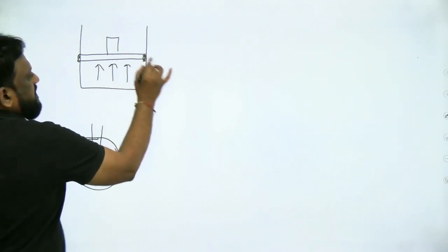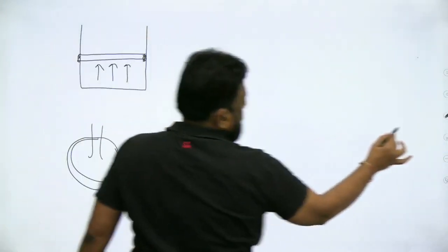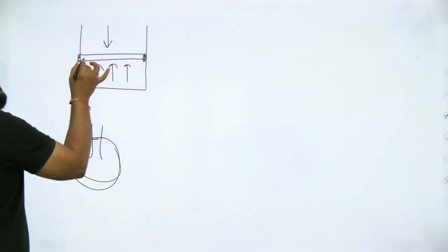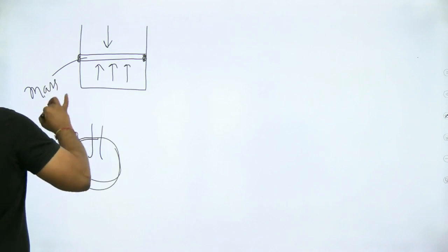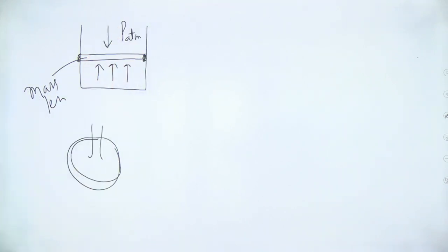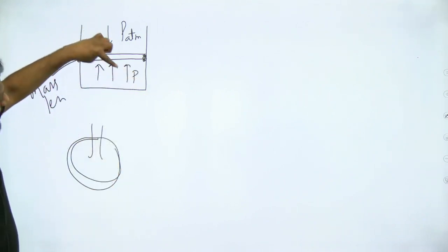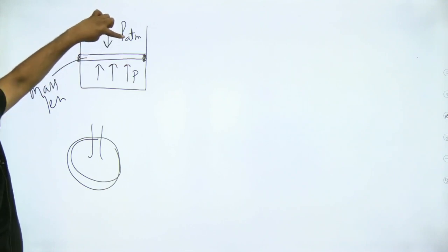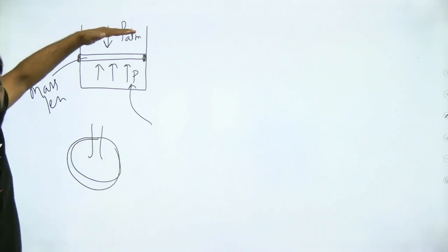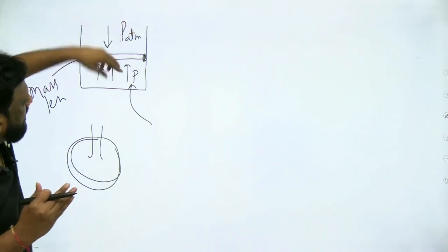It's a constant pressure process, no doubt about it. Look at what is the pressure. Let us say the piston is massless, and this is atmospheric pressure. Now inside the gas is exerting. As this is massless, for equilibrium, whatever the fluid pressure is, the same is atmospheric pressure. When I heat, the piston is moving at a uniform velocity. Assume that it is uniform velocity. There is no acceleration. So for dynamic equilibrium, this and this will be same.